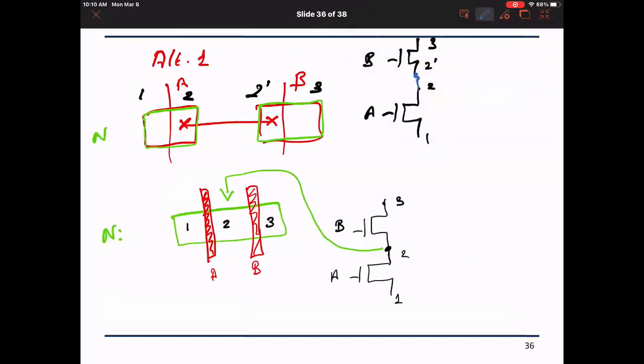I put a contact to connect them, right? So these two are the same, but this will take more area because I separated the transistors, whereas I could have benefited from lumping them together. Okay, because I could find a path that can walk through this. Okay? Great. So okay.